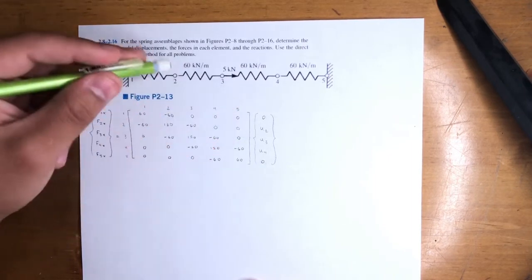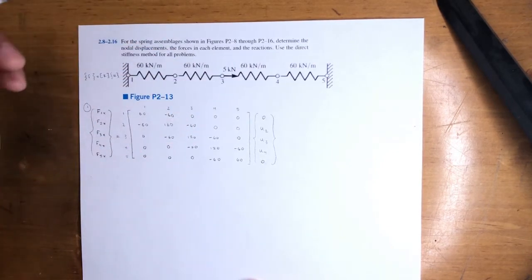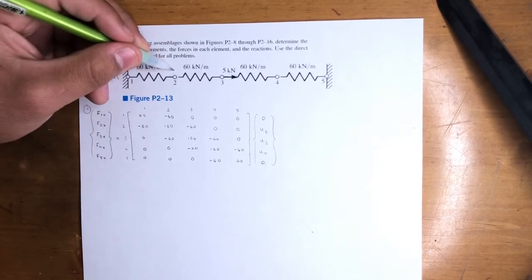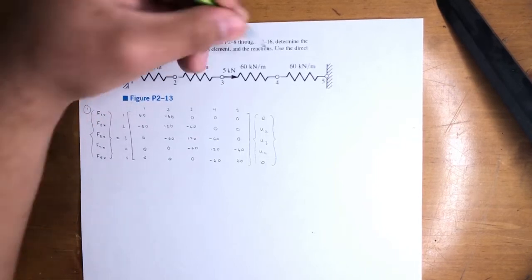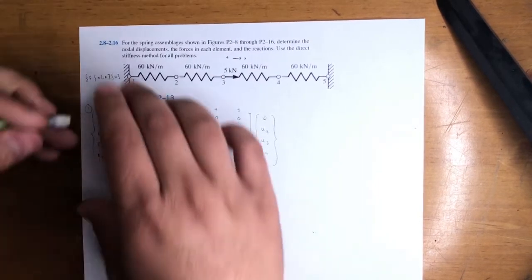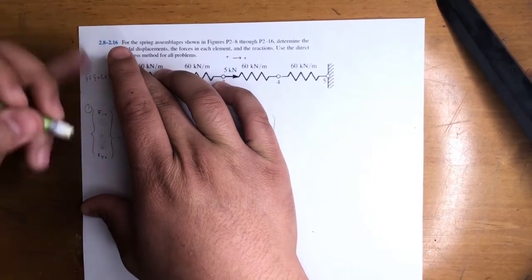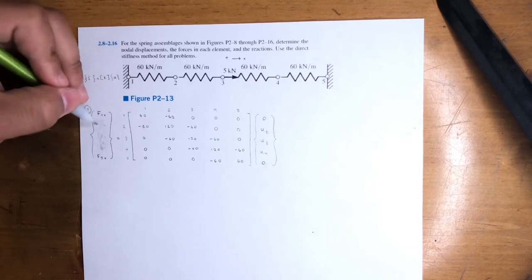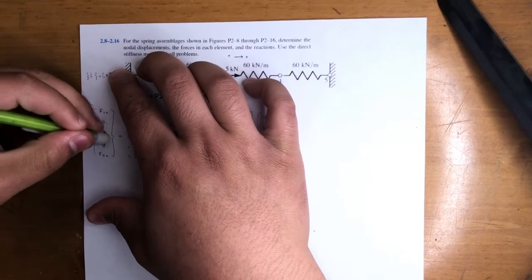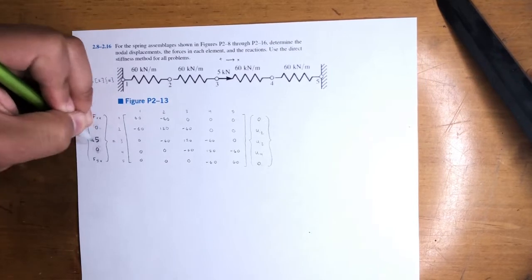Now, we don't know displacements at U2, U3, and U4, because when you apply the force here, these 3 are going to move. You don't know how much, but just by looking at the diagram right here, there's 0 force here. There's positive 5 going to the right, so positive X direction, and then 0 at 4. So these 3 forces right here, there we go. Looks a little sloppy, but it's 0, 5, and 0. I don't like that 5. This eraser is not the best. So 5. There we go.